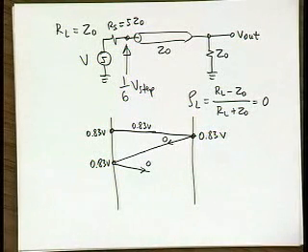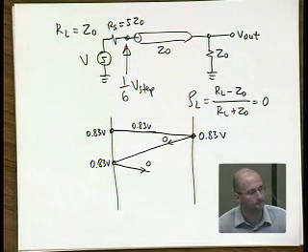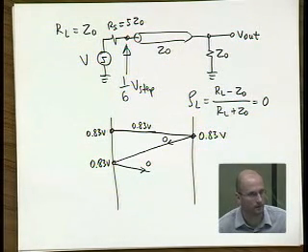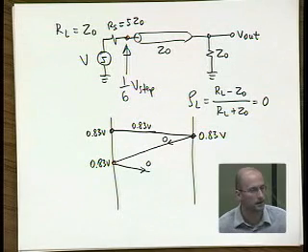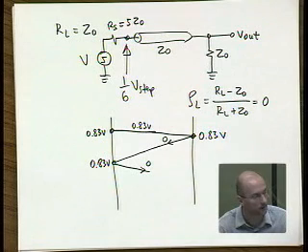In the voltage calculation, why do we include the reflected wave? I mean, you include the V last and the V incident, but why do we include V reflected? Because that's basically the wave that gets added to the total voltage at the output. When you have your incident wave, then depending really on your termination, that incident wave may get amplified if you have rho greater than 0, or it can get attenuated.